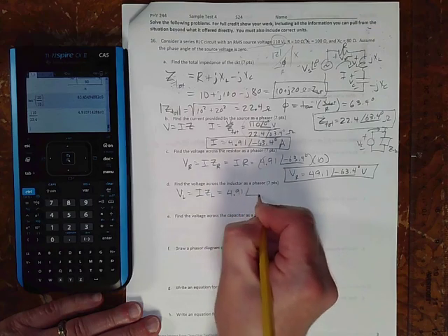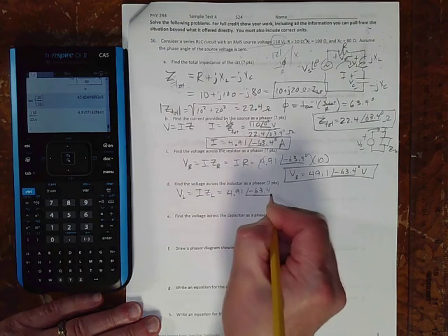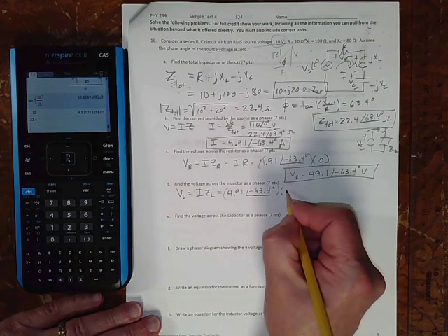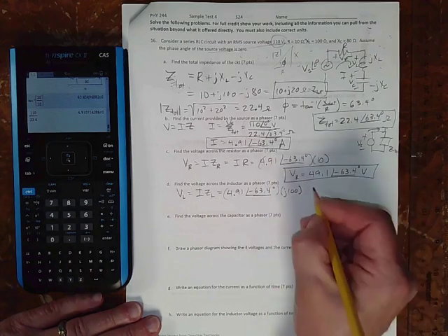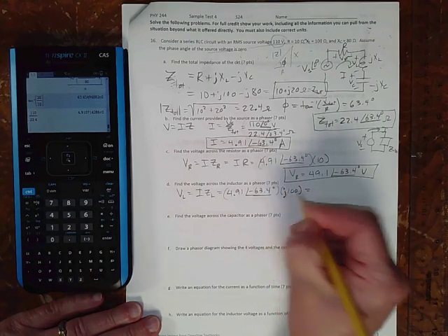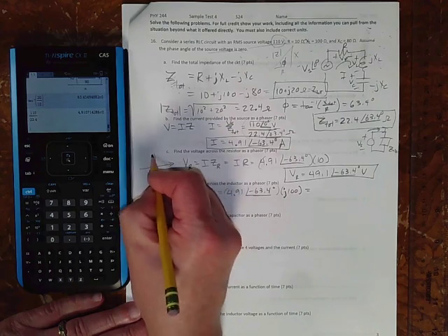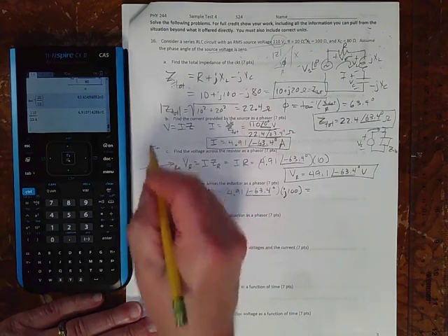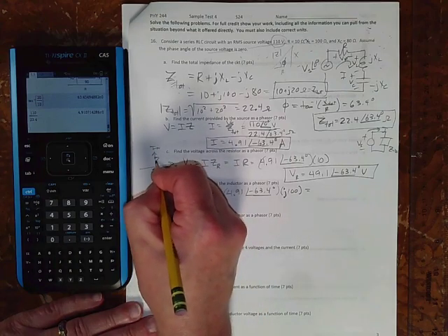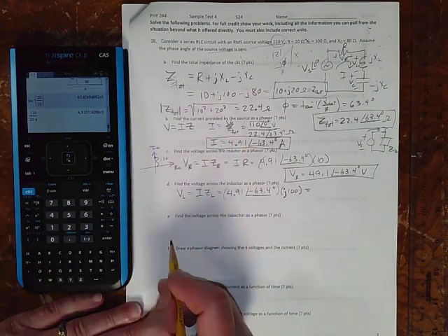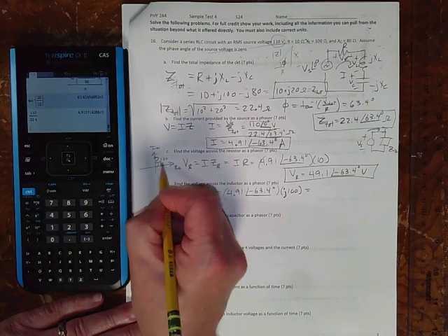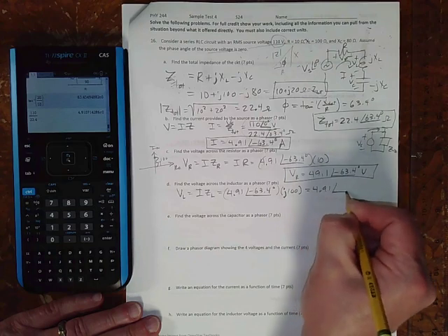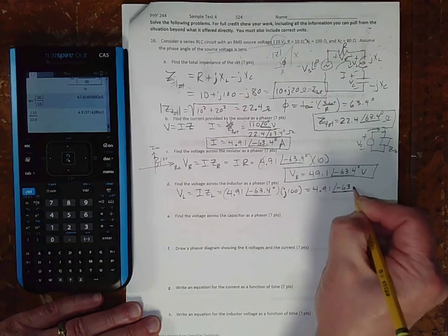Remember in our phasor diagrams, the imaginary part, the j component, is the vertical part, so this would be 100 up on this axis. In polar form, it's 100 at an angle of 90 degrees. Multiplying is easier in polar form, so let's put them both in polar form.